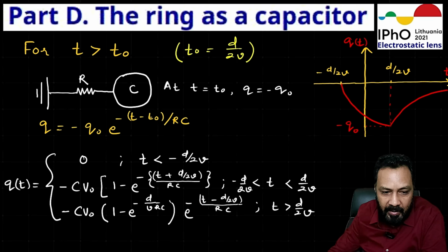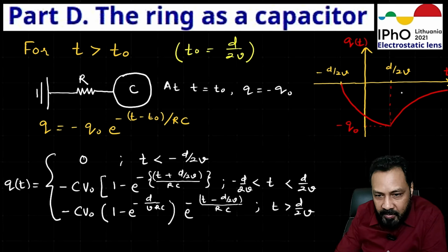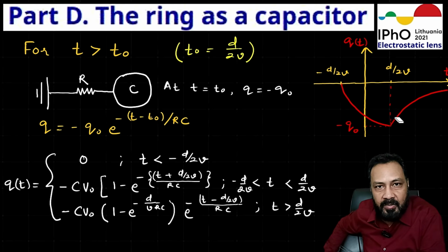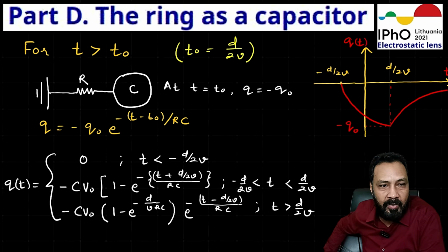But the question, I'll show the question, but let me explain this diagram. Suppose this RC is very small, this time constant is very small, so it is discharging very fast. And this diagram is not up to scale. So in one time constant, maybe in some millisecond, the charge remaining is 37%, that is 1 by e times. In 2 time constants, that will be 1 by e square. So after a few time constants, it will be practically uncharged.